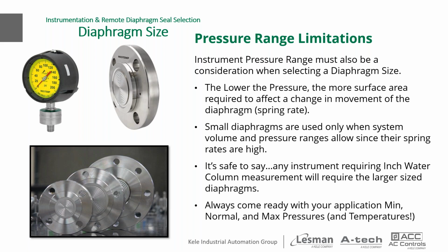When you're looking for solutions, when you come to us, if you don't have an application data sheet or an instrument data sheet, not a problem. Just always come ready with your application minimum, normal, and maximum pressures. And for that matter, the temperatures too. We need to know both.